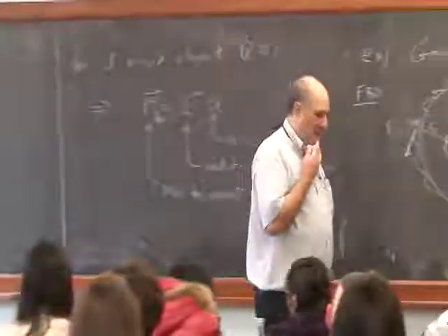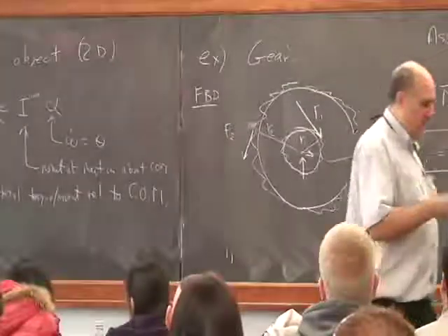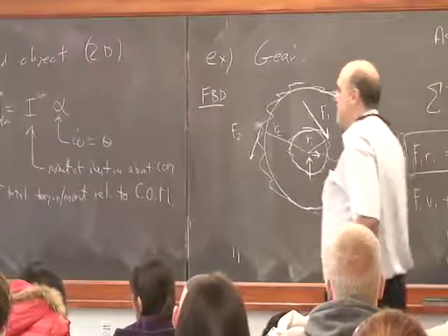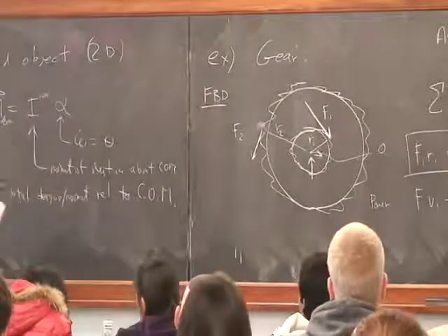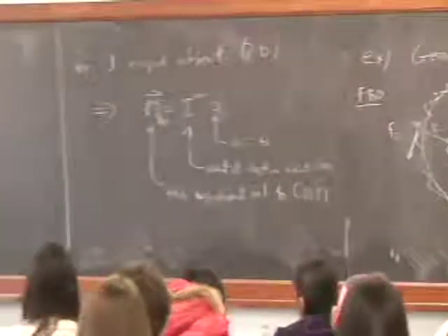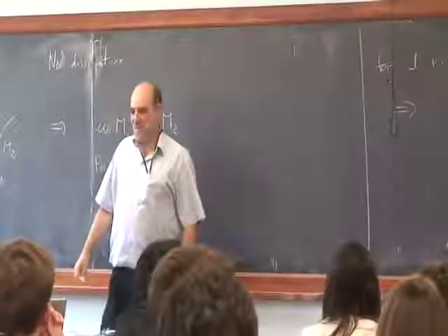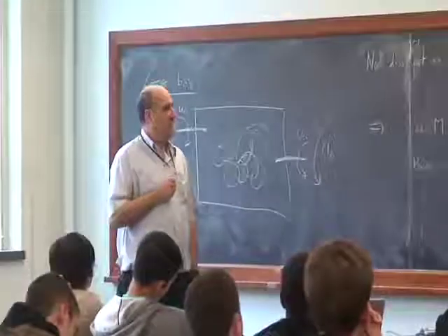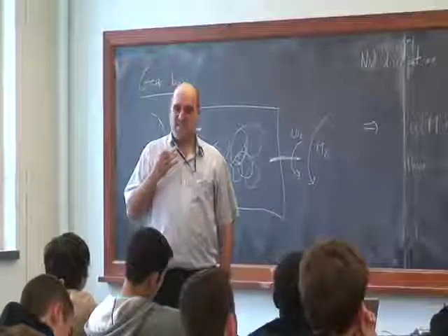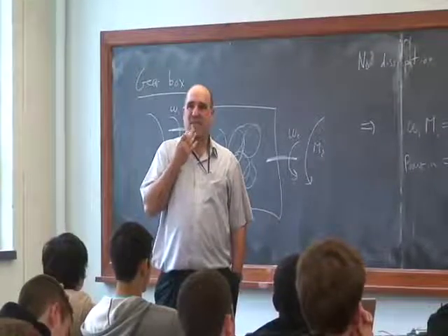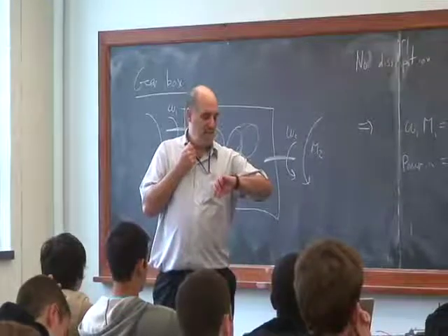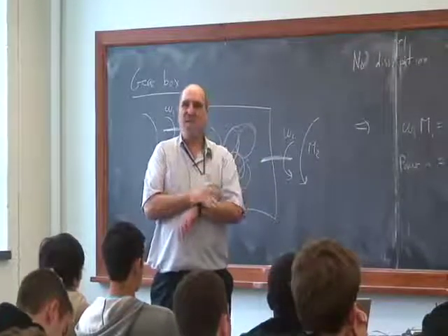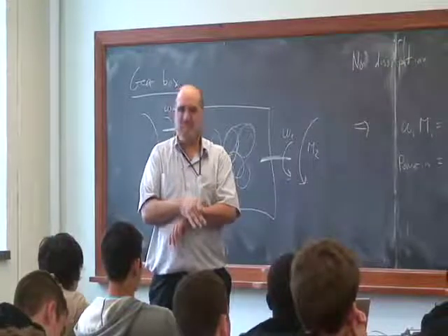We measured in my lab one time the whole transmission, including the rolling friction and so on, is about 93% for a brand new Kmart bicycle. Typical cheap gearbox that you buy with an electric motor might be as bad as 50% efficient. It might actually throw away half of the energy. Okay, so that's the basic story. What more you have to learn, I think I'll let you learn about electric motors by yourselves in the lab this afternoon.